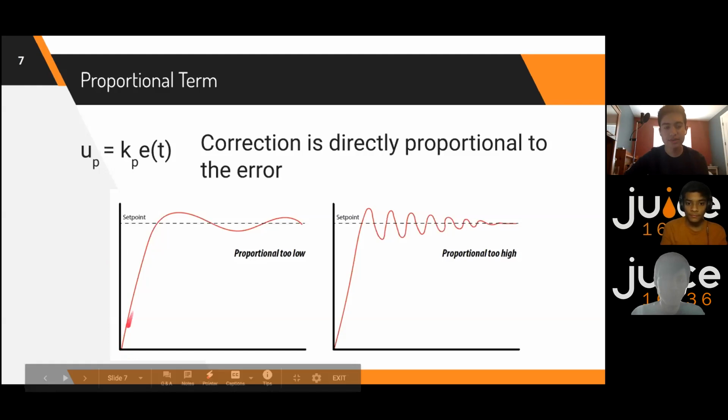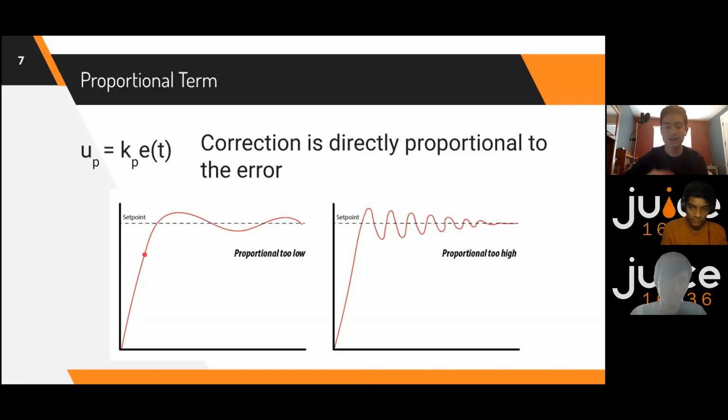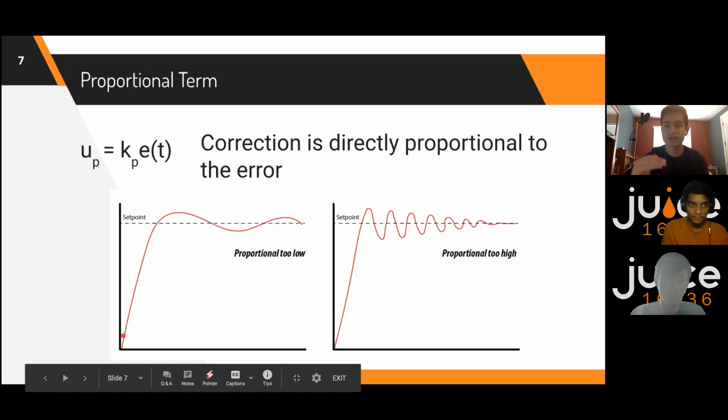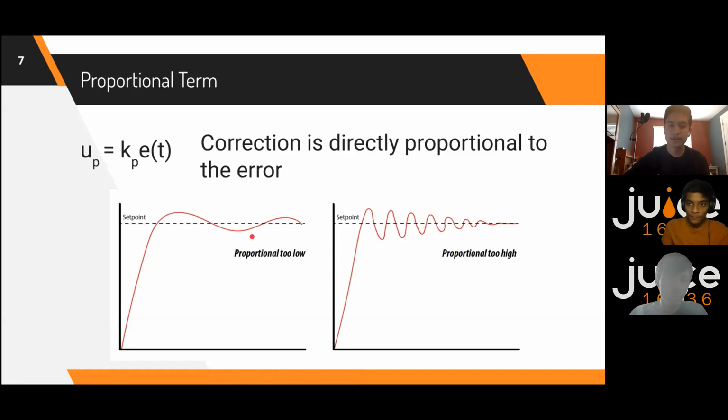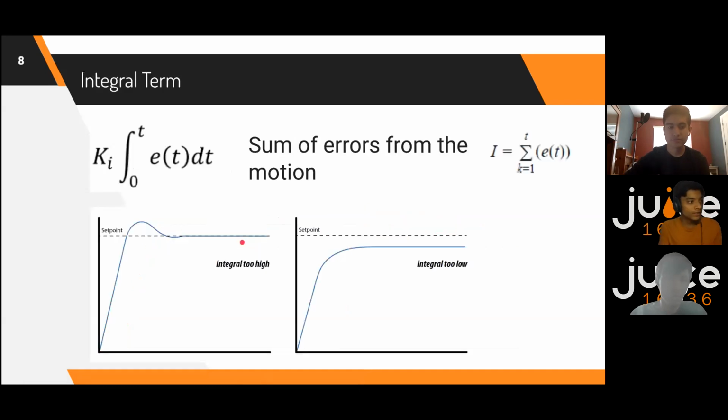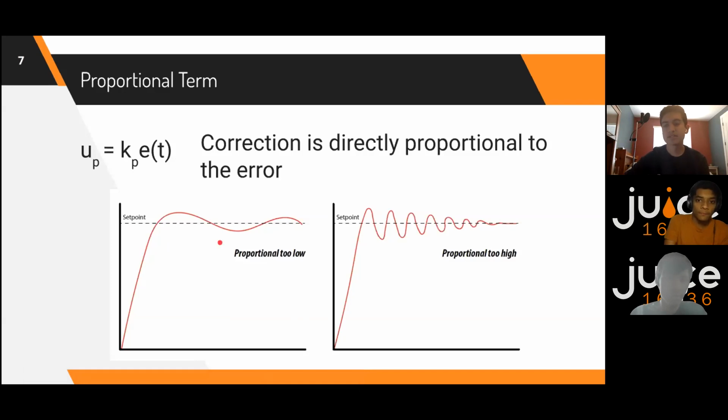So we found that the best tune is, if you can see my pointer here, that you start off with a medium amount of speed, and then it approaches the target without ever actually reaching it. So I'll address how you finally reach your target later, but if you do this tune, then it should be that the error gets your robot pretty close to your target without overshooting it. And when Sid says target here, he does mean target distance. Yeah, sorry, that's what I meant.